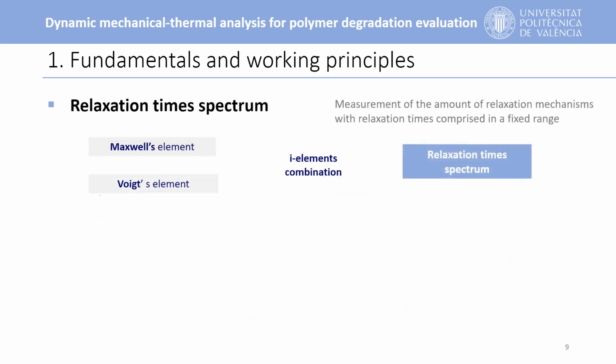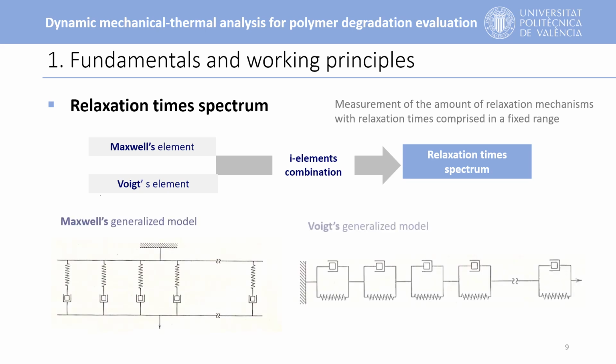All the previous slides have assumed that only one relaxation process can occur in a given polymer. However, viscoelastic materials are far more complex and have many relaxation processes. Therefore, models describing real viscoelastic solids are built as the sum of individual components for explaining all the relaxation processes in a given material.